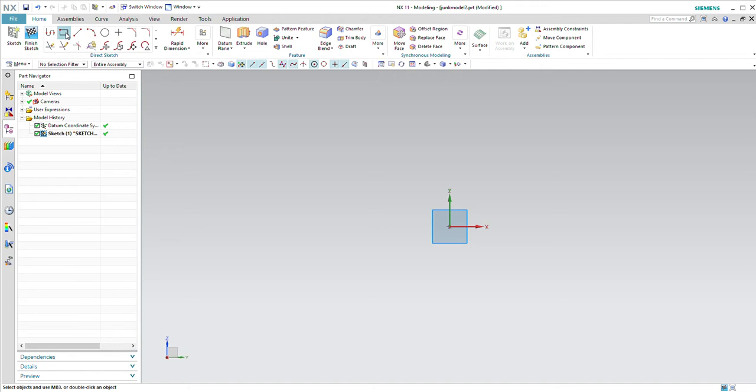I'm going to create a beam with a rectangle cross-section, so I'm going to do that here by hovering, and so it's going to pick that point. I'm just going to click the mouse there and say OK to that, and then as I drag, it's going to size the box, and this is going to be the end of my beam.